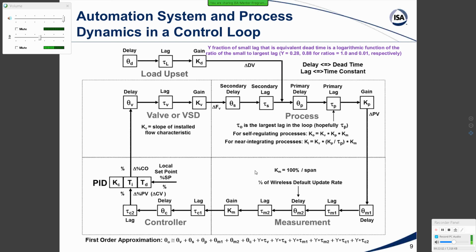You want to understand what creates nonlinearity by realizing that we have a product of gains going on here, and also in terms of trying to maximize the open loop time constant being the primary lag. And this is the principal source of disagreement in process control.